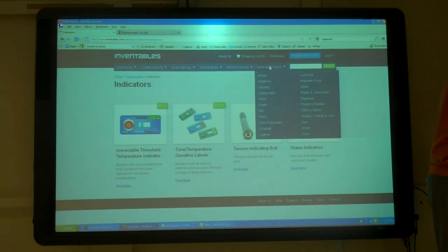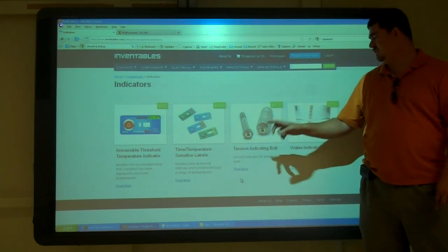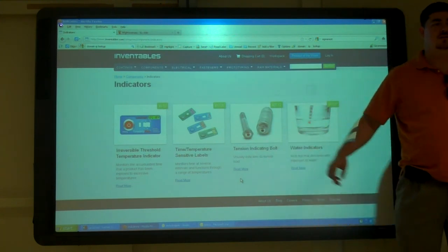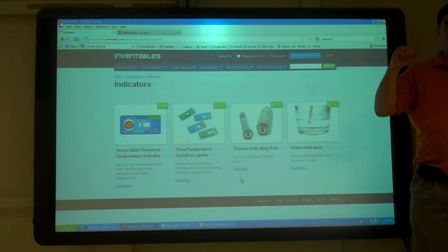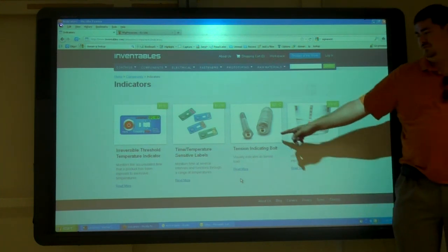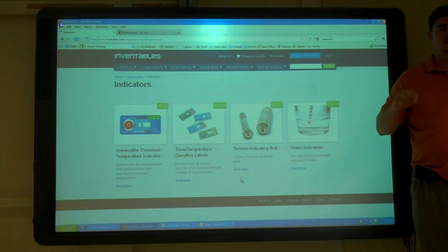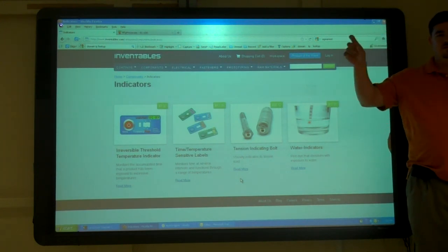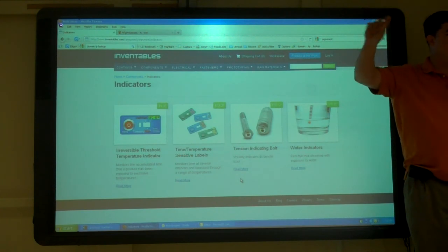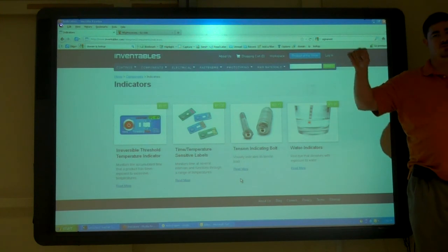And then over here, under what? Yeah. You can buy those. When you get to a specific torque, there's a thing on the head that changes color. You don't have to use a torque wrench. They're extensions. I have ratchet extensions that do that. Yeah, it's the same thing. So it makes it kind of dumb-proof, right? You don't have to have someone set up or calibrate the torque wrench. They put in a 50 foot-pound rated bolt. They turn it till it turns red, and then okay, now it's the right torque.